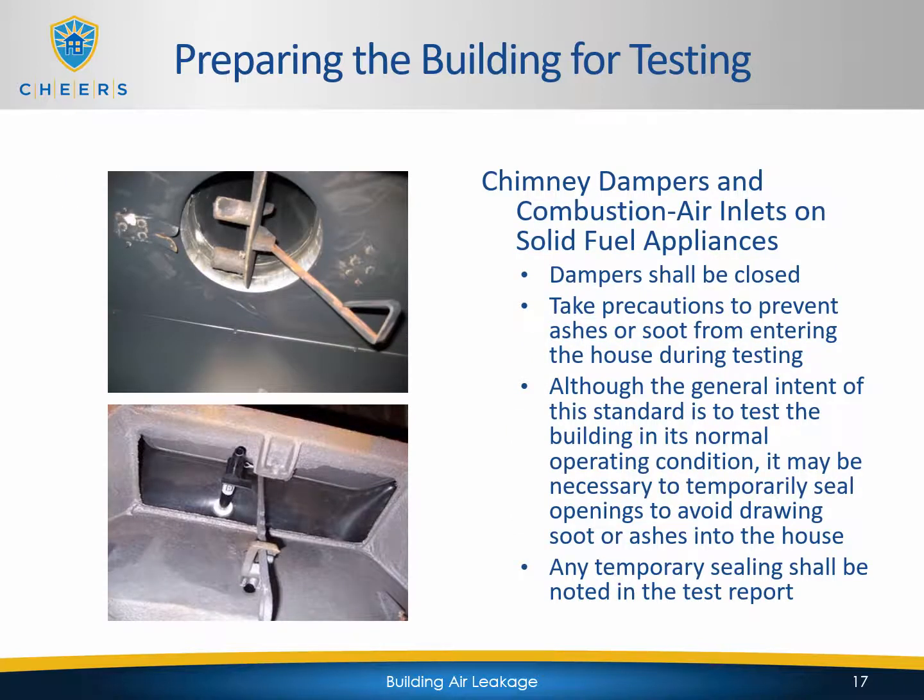Chimney dampers and combustion air inlets on solid fuel appliances: the dampers shall be closed. Please take precautions to prevent ashes or soot from entering the house during testing. Although the general intent of this standard is to test the building in its normal operating condition, it may be necessary to temporarily seal openings to avoid drawing soot or ashes into the house.